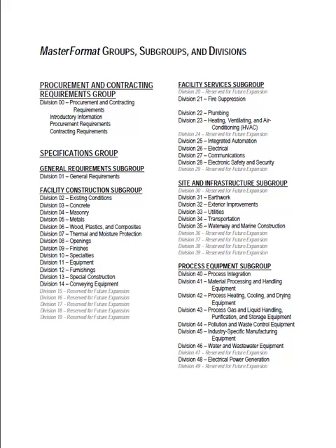I do have attached to this a set of specifications from a job that was done a couple of years ago, and we'll take a look at those. Looking down through the list, here we get into our meat and potatoes, basically, of our specifications. Division 2 is existing conditions, concrete, masonry, metals, wood, plastic, and composites. This would include any structural wood, insulation, or actually insulation's under thermal and moisture protection, any type of composite material, laminated beams, anything that would fall in this division would be basically your framing materials.